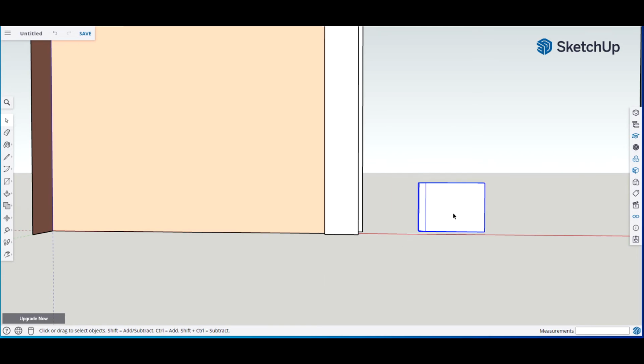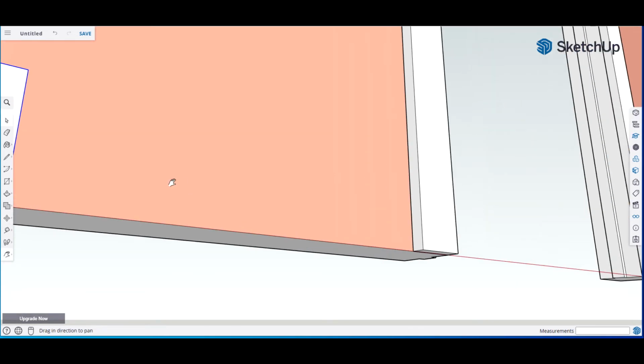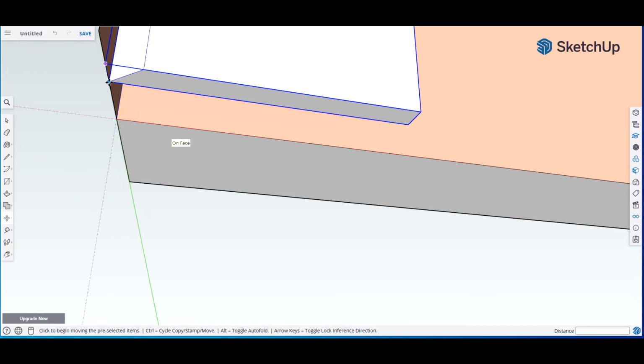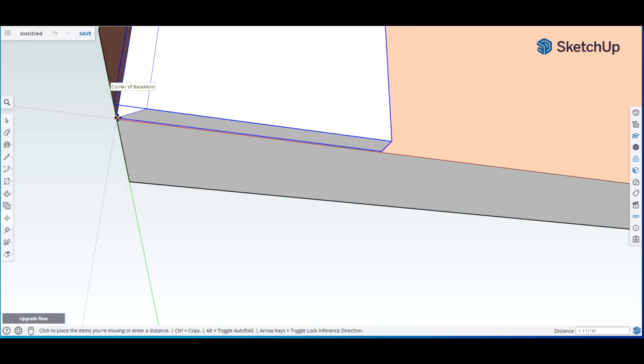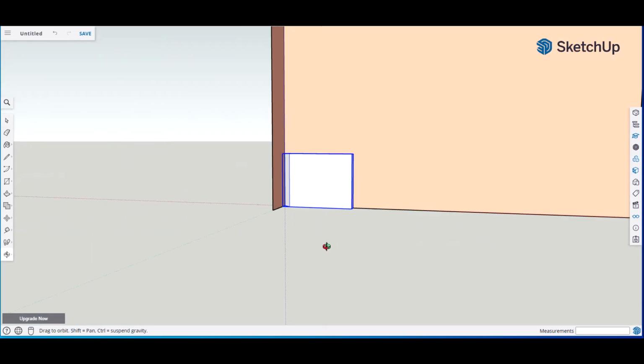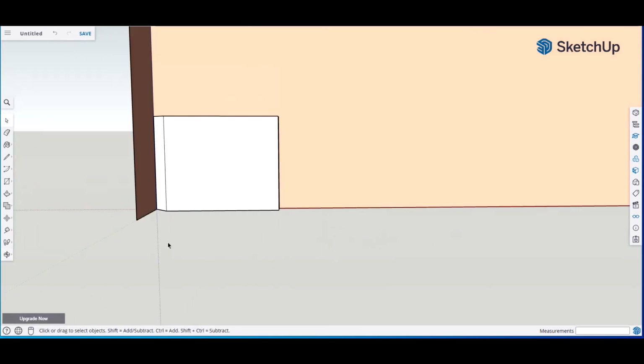All right, so let's go ahead and attach that to this. We're going to highlight it. We're going to hit M, and then we're going to bring it over to here. Hopefully we can snap into place, but we didn't here. So let's go ahead and zoom in, H, zoom in, M, and let's grab this corner here, and now it's snapped in. Spacebar, zoom out. That's snapped. So we have it snapped in place here.